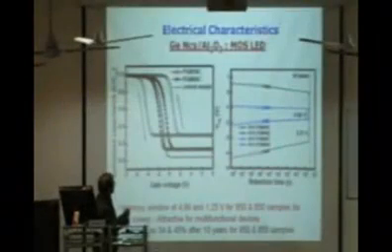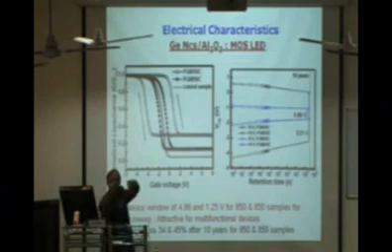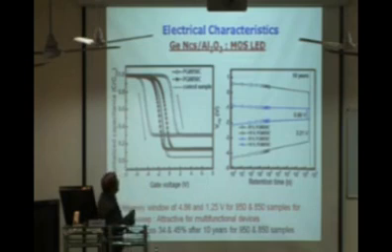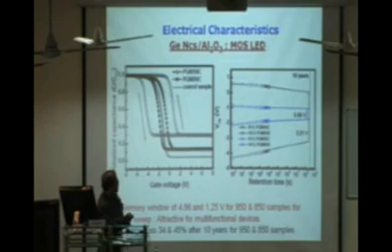And ultimately, for the device people, you have to show that this charge should not leak, because this quantum dot is embedded in a very good insulator. But as you know, there are always some defects in the insulators. So since there is a little bit of defect in the insulators, this threshold voltage comes down as a function of time. In fact, we do the measurements up to 10 to the 4th cycles and extrapolate up to about 10 to the 8 cycles, and we still see a good hysteresis width. That shows this can be usable; in fact, a lot of companies are now making silicon-based nanocrystal memory.